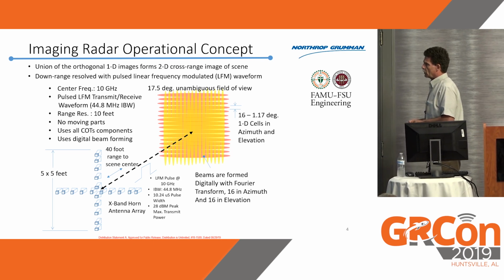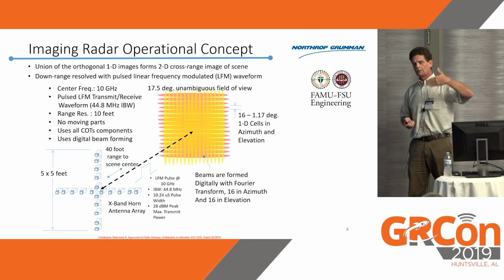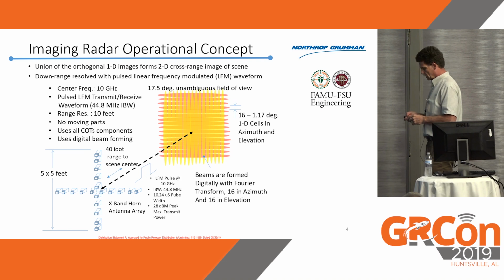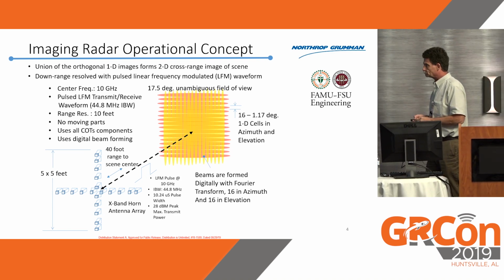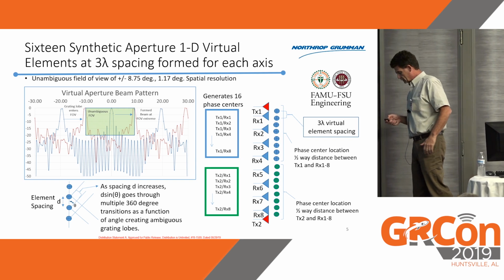We're going to be sending out a pulse. It's pretty long. It's 10 microseconds long. With the range only 40 feet away, that's like a 10,000 foot pulse. So we're going to be transmitting and receiving at the same time, so we really have to separate those two returns.